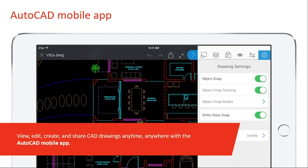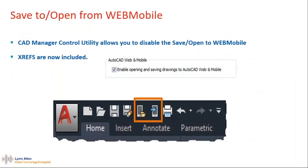You saw I showed you those two tools. Is that my next slide? It is. There's the save to WEBMobile, and there's the open from WEBMobile, so that you can then open up the markups that you did and then make changes accordingly. And I have those two tools highlighted here on the screen. And now a couple of things. So there were some CAD managers who did not want that save and open to and from WEBMobile to be on the quick access toolbar. And so you will see that with the CAD manager utility, you have the ability to disable that if you want to. Just letting you know, if you're not going to be using it, or if it's caused you grief, you can definitely disable that.